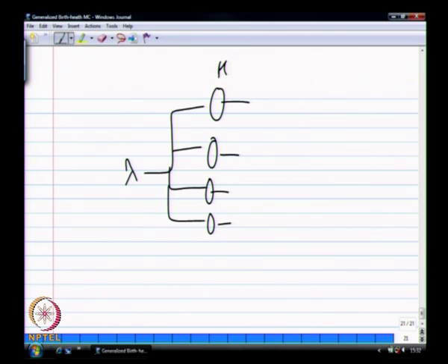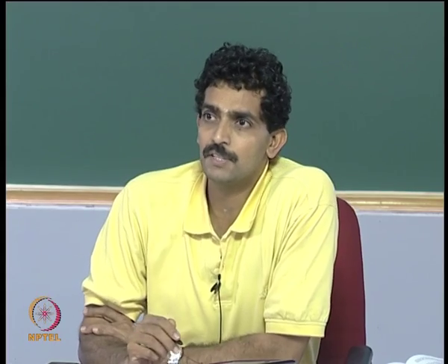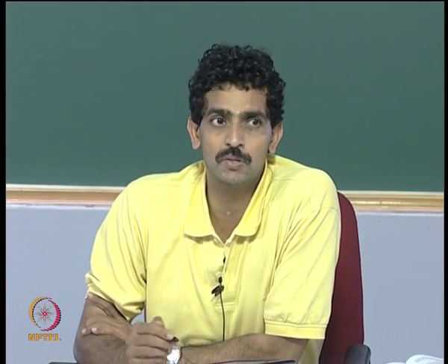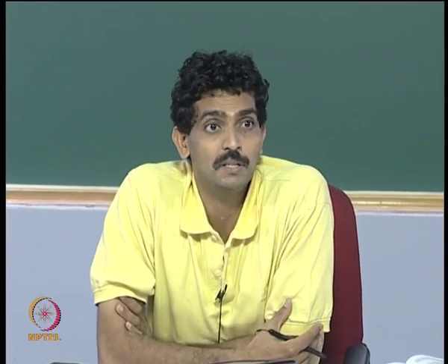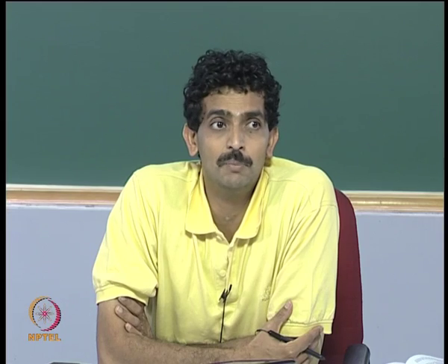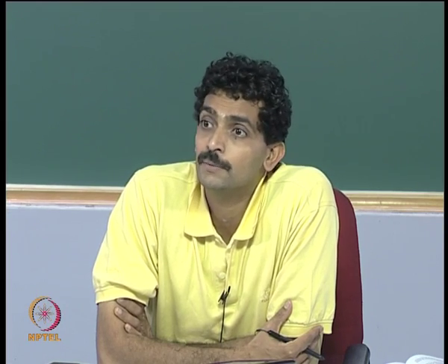We saw this in TDM also, because if we have 24 slots in a TDM frame, and all slots are used, you cannot be given any other slot. So the goal is to derive what is the best M, right. This is very important for telephone networks. All this came about with designing telephone networks, way back in the 1900s and 1920s, where you need to decide some good value for M. How many circuits should I have in a system such that the customers do not get annoyed, right.